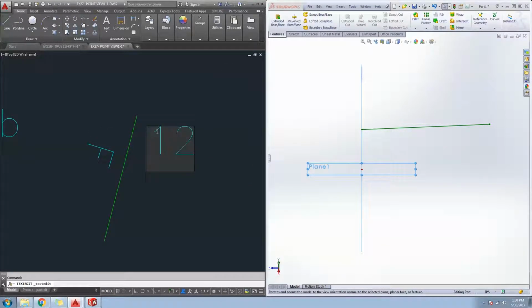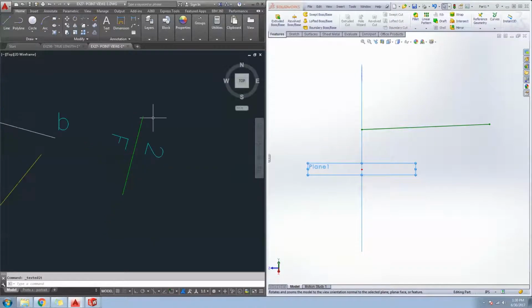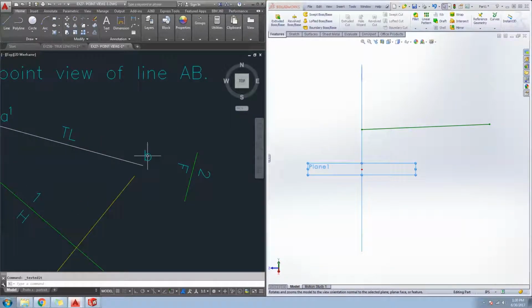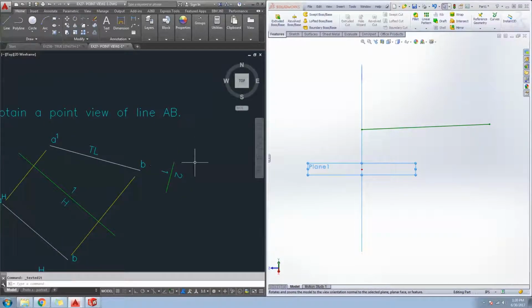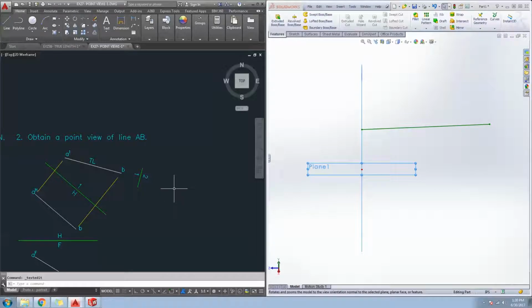This is going to be plane number 2 because we've already used auxiliary view number 1. That was this guy over here. And this is going to be auxiliary view 1. So 1 and 2. Here's the view I want. So I'm going to count 2 views back, 1 view back, 2 views back. I'm going to do my offsetting from this view here. So offset. Point B to that folding line, B to that folding line.